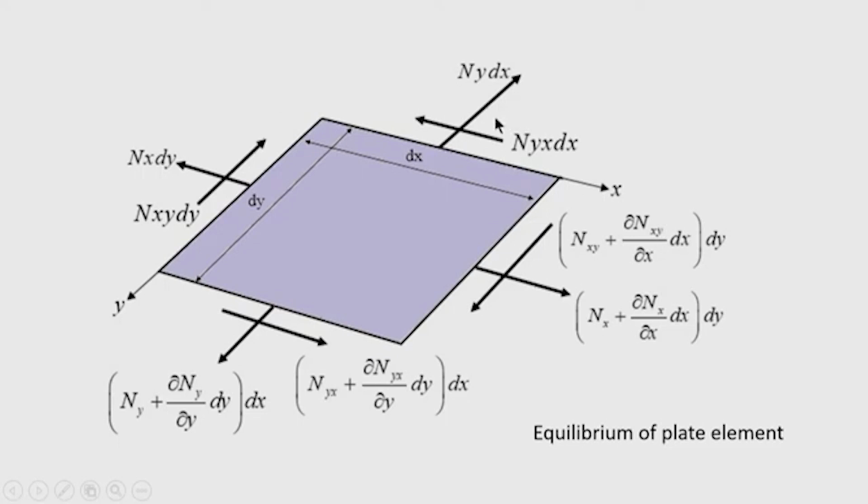So, in-plane forces are actually Nx, Ny and Nxy, and by virtue of the complementary nature of the shear force, Nxy equal to Nyx. So, that we will take in case of derivation. Okay. Now, here in this figure I have shown only the in-plane forces, no other forces are shown, because I want to find out the interrelation between this Nx and Nxy.